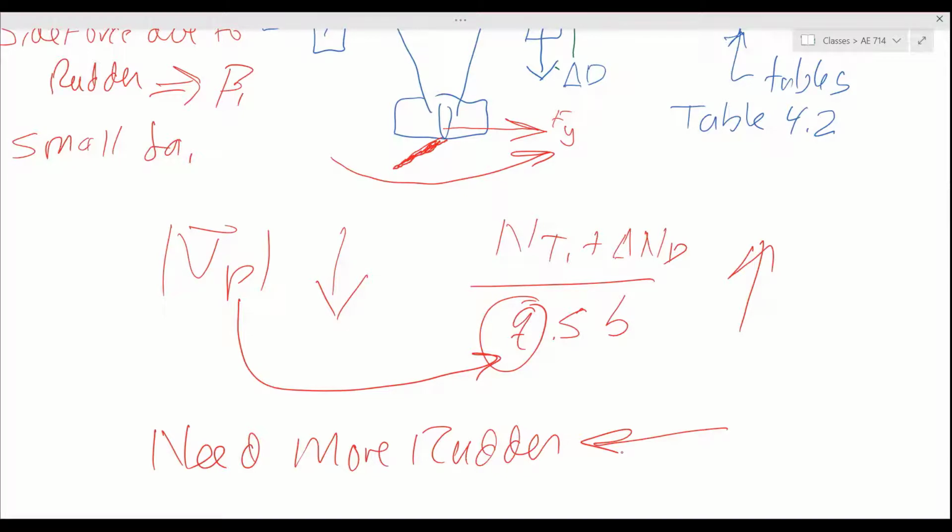The engines were at max thrust to climb, and that's when an engine failed, and so he got the maximum yawing moment out of the engine, and he was going slow, so the rudder was at its limit as far as being able to control the airplane, and he got too low and too slow and stalled out and crashed.